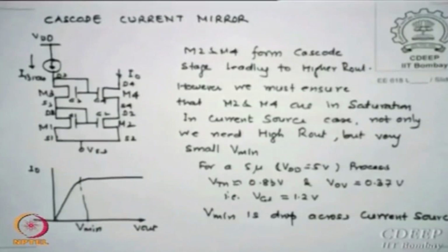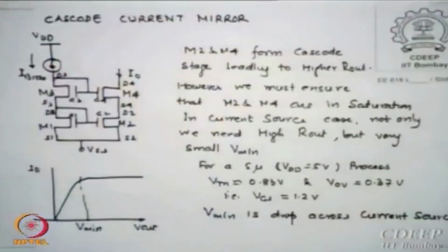In most cases the source body is grounded and not connected to the source, okay. They are generally grounded, but there are technologies in which it is connected as well. So VSB effects could be taken care of in case this is not connected directly but to a ground. If it is a ground, that means there is a potential there and some VT will move, okay. So that part will be there, but right now I am not considering the VSB effect, but it can always be brought into the expressions. Maybe I will give an example when I bring that expression. Is that okay?